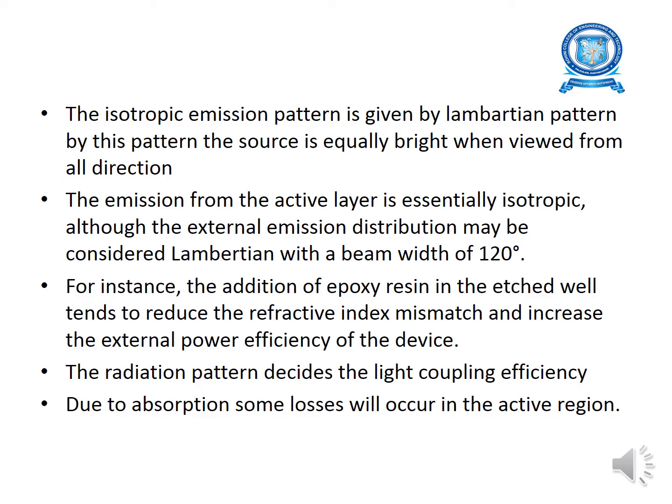The addition of epoxy resin in the etched well tends to reduce the refractive index mismatch and increase the external power efficiency of the device. The radiation pattern decides the light coupling efficiency of a fiber to the light source. Due to the absorption, some losses will occur in the active region.